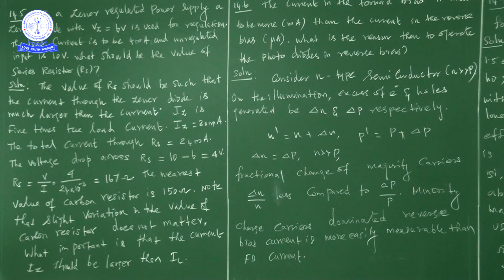You already know the resistor series and parallel theory. When any instrument is connected parallel to a resistor, the potential is constant. Here in the Zener diode as a voltage regulator diagram, the Zener diode is connected parallel to the load resistor, where we are taking the output.